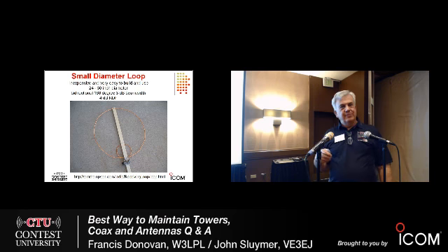People that build Yagis use the correct term for this. This is actually a hairpin. There's one loop here, and the small loop is soldered to the open connection. All it does is raise the impedance at the feed point of the larger loop. So this doesn't have to be in a loop shape at all.